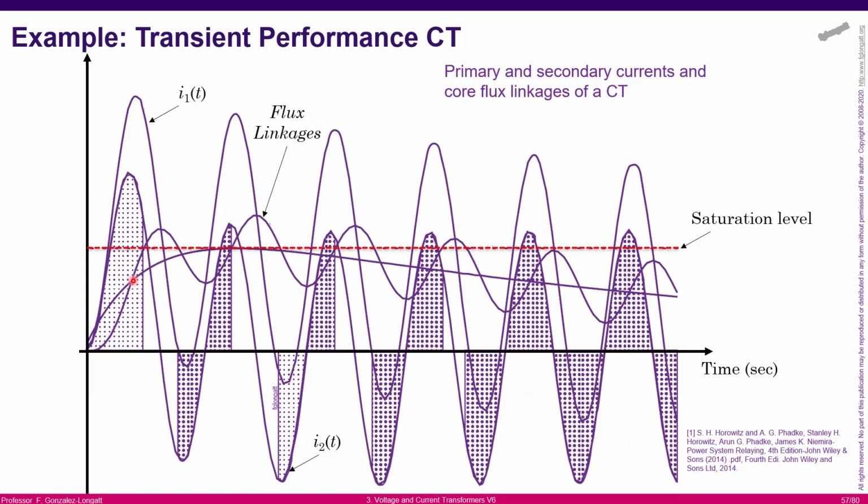Okay, then we have another two plots. The second plot is the current on the secondary. You can see here the current at the secondary. Of course, there is a phase angle between primary and secondary. As I said before, usually we don't take into account that phase angle, at least the manufacturers say that. In the previous example we didn't, but in real life there is a small phase angle. You can see there is a very small phase angle, but it's there. There is a difference between the current instantaneous value at the primary and the secondary, and that creates a phase angle.